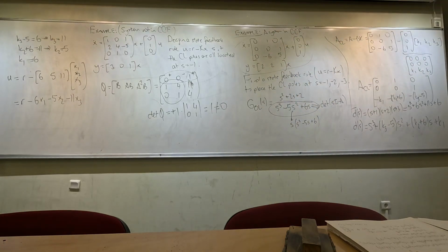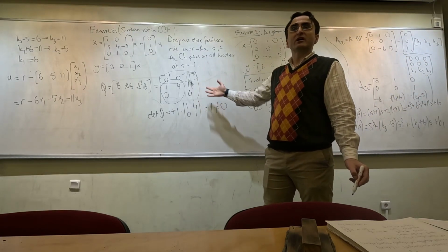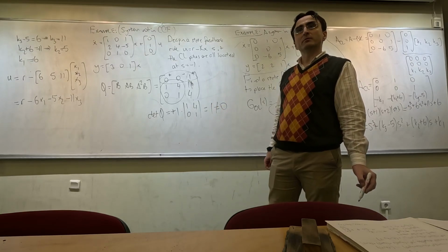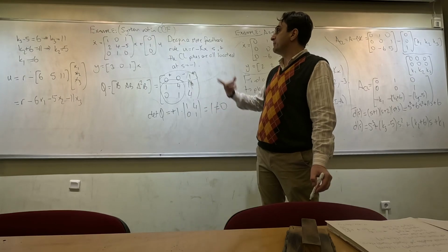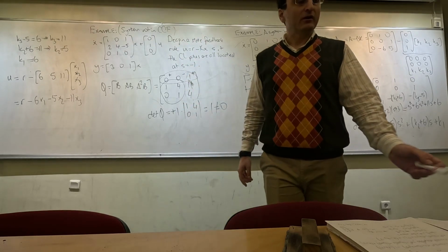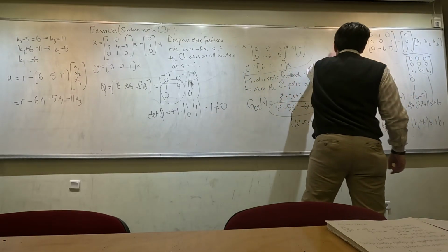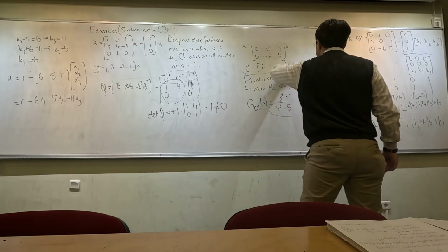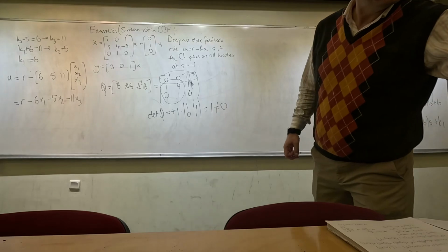So in this case, definitely I know that the state feedback problem has a solution. Okay? It is not an infeasible problem anymore. I know that I need to be able to find k1, k2, k3 values, which is going to place the eigenvalues at these desired locations.